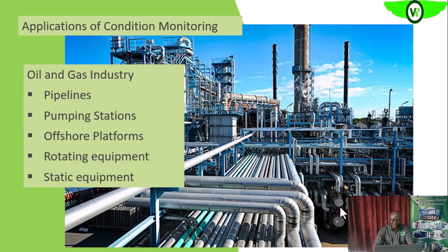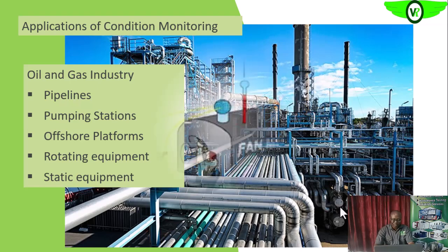Static equipment, like we explained before, your heat exchangers, heaters, and boilers, we can use technologies like infrared to look at them, even to look at the flue gases. All of this will give us an indication as to what is happening within the equipment.